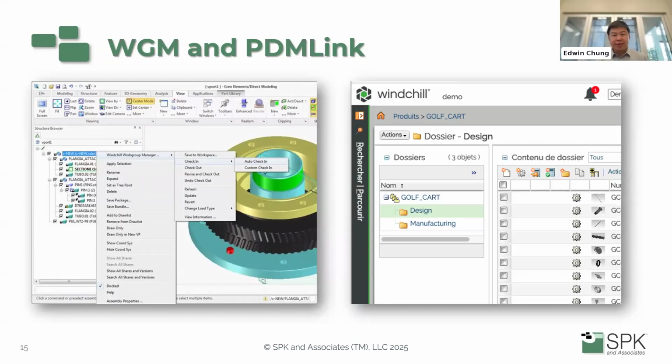That works for Creo, but for everything else there's a separate program, Windchill Workgroup Manager, often referred to as WGM. That's a client-side companion that will plug into other CAD tools like SolidWorks, AutoCAD, Cadence, and others, and then allow engineers in those other tools to also check in and out, manage versions, and see lifecycle state for files from those programs. Workgroup Manager also exposes certain Windchill tasks such as searching, product structures, change actions, and BOM relations. I talked earlier about that problem that they solved using Workgroup Manager.